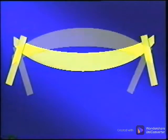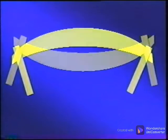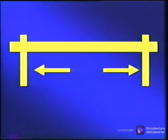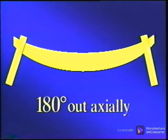The bend causes one side of the rotor to be longer than the other, forcing the bearings out during part of the rotation and letting them flex in for part of the rotation. This makes it appear as if the ends of the shaft are moving in opposite directions, while for a straight shaft the ends are moving together. The phase data for a bent shaft, then, will be 180 degrees out in the axial direction from one end of the shaft to the other.